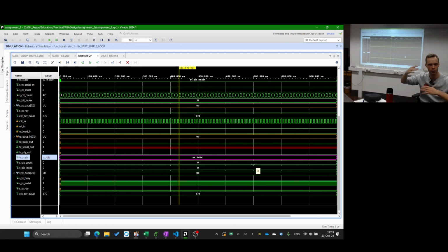So this might help you if you want to have signals next to it, because this looks a bit blurry, right? In the ideal case, when I'm done with my design, I will have no X's. I might have some red signals, might have some orange ones, because they can be undefined. As I said, I might choose that I don't want to assign a reset there, because eventually, throughout my process, it will be assigned. If it's unassigned until the end, there's most likely something wrong, or I don't touch the signal for whatever reason, I don't reach a state, those kinds of things, because logically, I don't want any signal not being defined in any way.